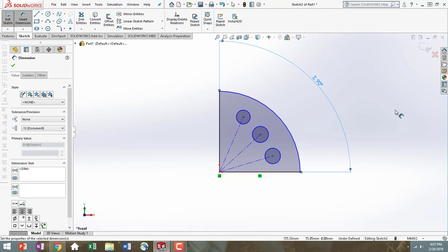If you're worried that you're not using your global variables correctly, you can always see if you are using a global variable because the summation sign will be in front of it. So there's my A1. I'm going to work my way over. So I'm going to put in my angle right here for A2.